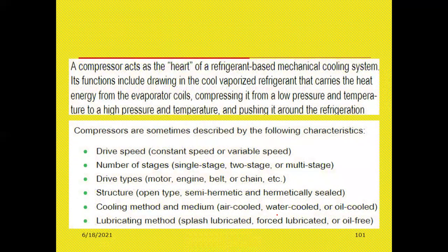Next, a compressor will act as the heart of a refrigerant based mechanical cooling system. If you take a refrigerator at home, or an AC at home, what is the heart? The heart is the compressor. The compressor will act as the heart of a refrigerant based mechanical cooling system, and its functions include drawing the cool vaporized refrigerant that carries the heat energy from the evaporator coils.